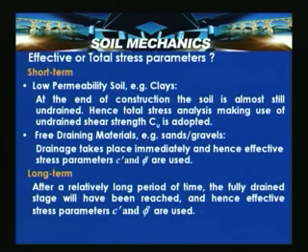The short term stability conditions are basically valid for low permeability soil, for example clays. At the end of the construction, the soil is almost still undrained, hence the total stress analysis making use of the undrained shear strength Cu is adopted.